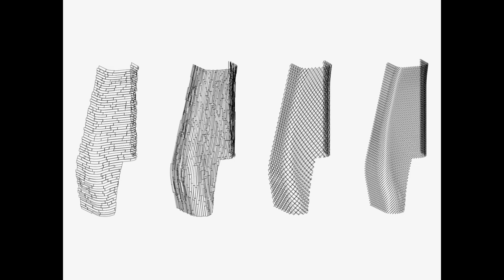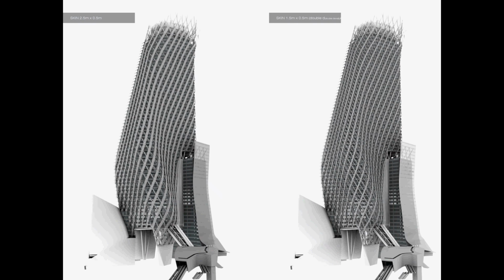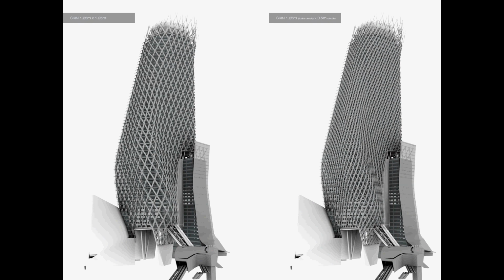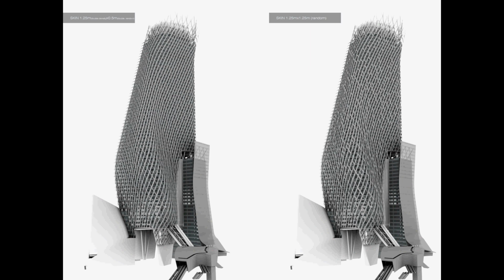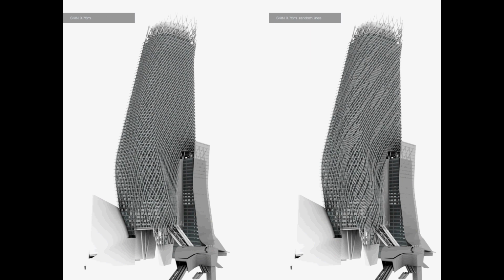The design process of the facade starts with testing tons of studies with different parameters. In this case, testing horizontal panels, vertical panels, diagonal, etc. Once it sets a certain direction, I also add some patterning on top of it. And then by changing parameters, any other pattern can be studied. I mostly worked in Processing, and with a certain coding structure you can switch or swap a certain module, code or function and change the parameters, and then you can generate many variations quickly.